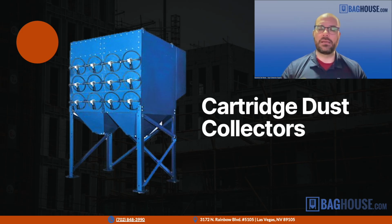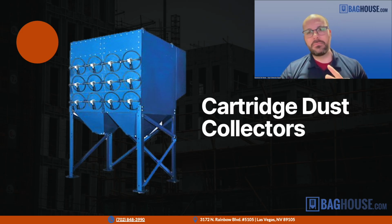In mining and cement, we don't see them used so much because most applications for mining and cement have a lot of dust that comes in. Cartridge collectors are especially good when we have a lot of air to clean that has a little bit of dust in it. In those applications, they absolutely make sense, and they can be a lot cheaper than a baghouse style.